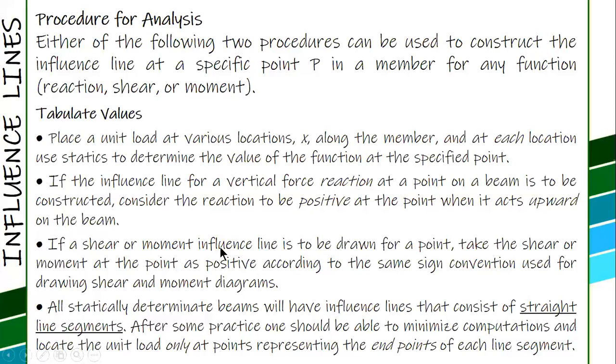If a shear or moment influence line is to be drawn for a point, take the shear or moment at the point as positive according to the same sign convention used for drawing shear and moment diagrams. That is for shear and moment.